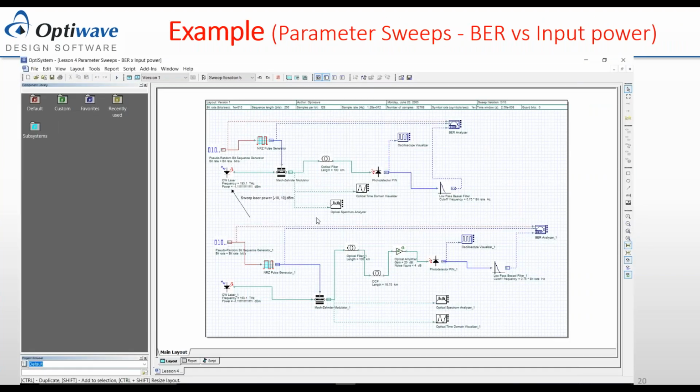This is one thing. The other thing is, if you go to the detector, as we mentioned yesterday, you can choose the noise sources you want to have: shot noise, thermal noise, or, for example, the dark current. You can also control the responsivity, which you can enter as data from the vendor, so it will be wavelength dependent, or it can be constant across all wavelengths. So these parameters, as we showed yesterday, you can have some control over.